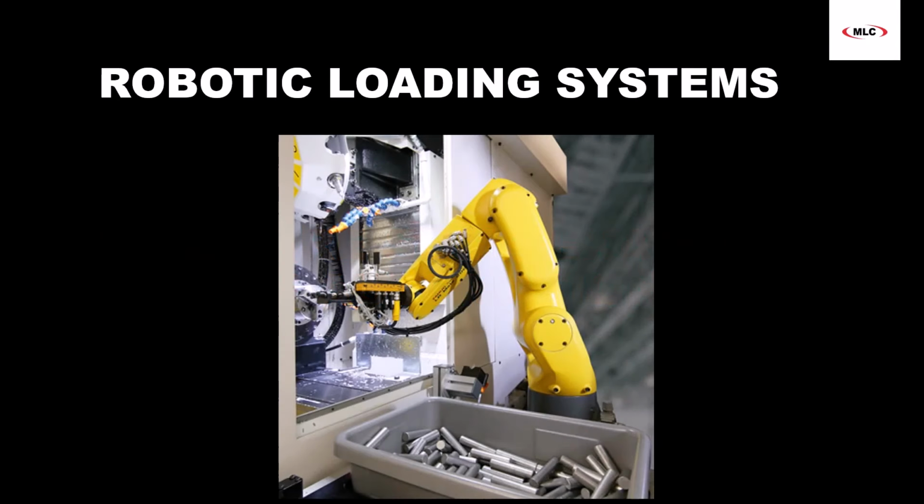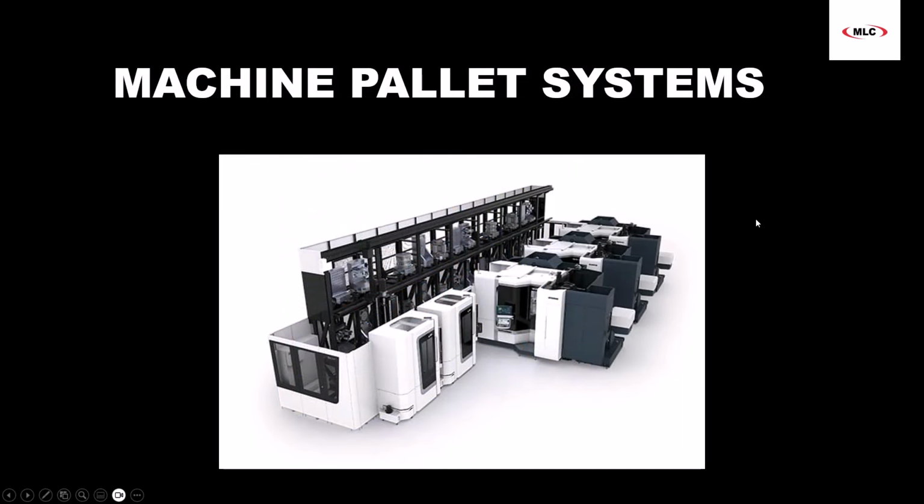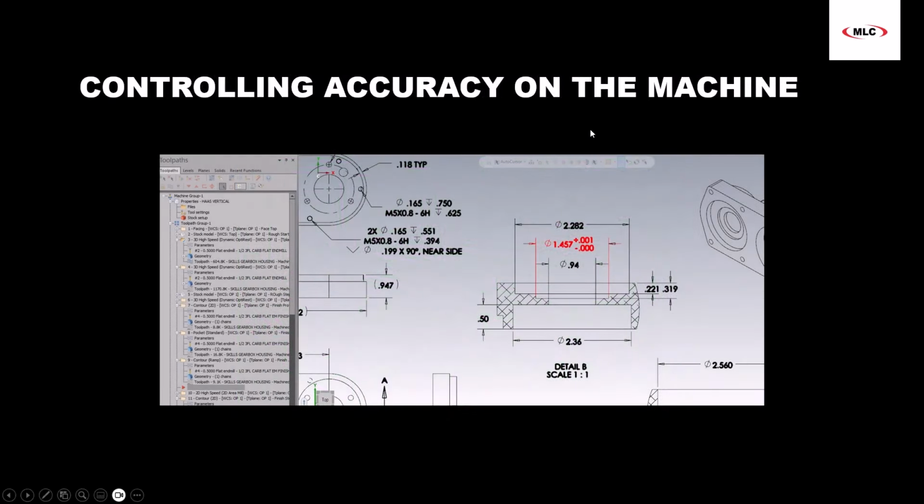Some of the more common examples would be a robotic loading system, using a robotic arm to load and unload parts from the machine. Other examples could be a pallet system, a pallet pool or linear pallet system that is loading pallets in and out. More examples would be lights out machining, doing as much as you can unmanned overnight. And lastly, making sure that we're controlling the accuracy on the machine itself. Maybe we have to hold tight tolerances, and we want to make sure that those are being held.